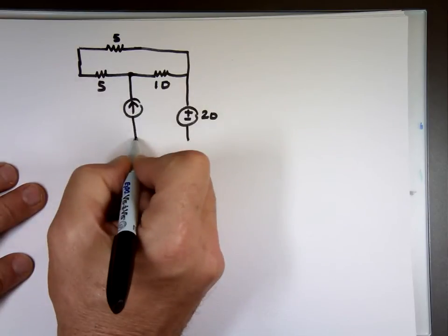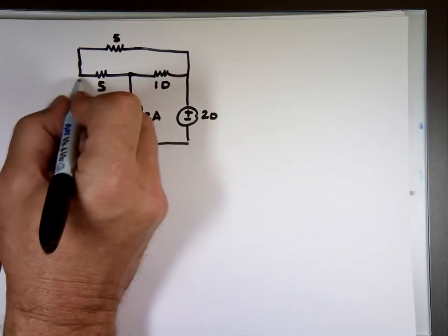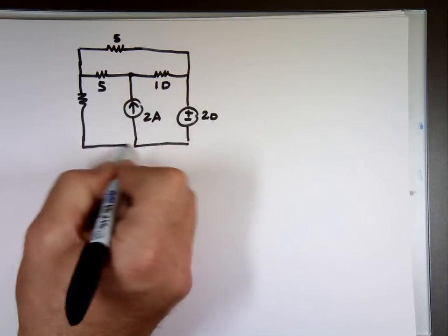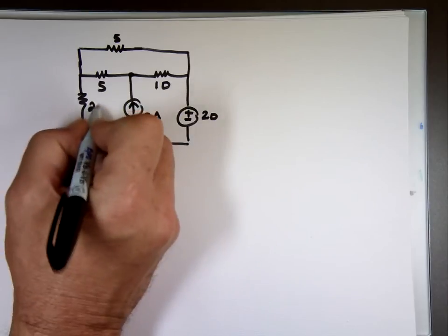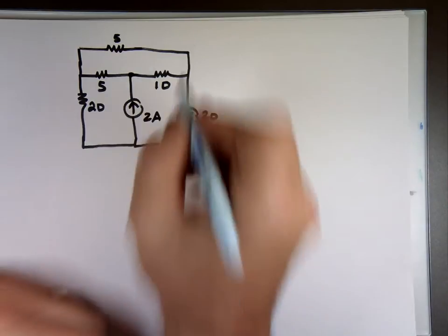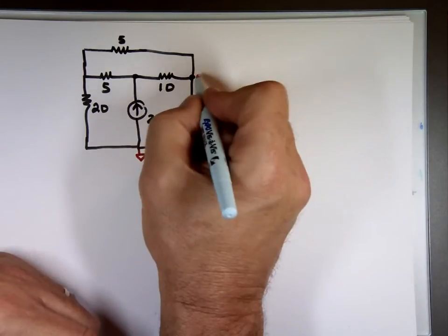And notice I was specific about what method to use. I want a certain method to be used because I want to make sure you know all the methods, which some of you ignored completely because you get used to one method. That's the one you feel comfortable with, and that's what you want to use. And I picked that method intentionally, use loop analysis. That means KVLs. And the reason I chose this is because it will make it 2 equations by 2 unknowns. You know, if this is my ground, you know what this voltage is. That's what? Negative 20.